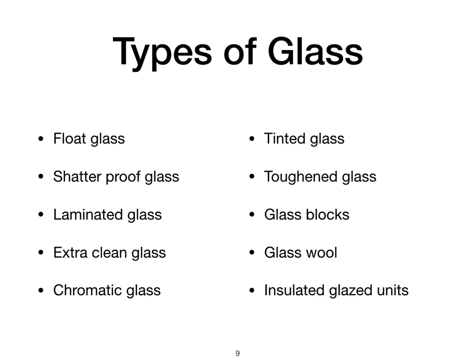Tinted glass. It is nothing but colored glass. A color producing ingredient is mixed to the normal glass mix to produce a colored glass, which does not affect the other properties of glass. For example, coloring ions like iron oxide, sulfur, manganese dioxide, cobalt, chromium, titanium, uranium are used as coloring agents, which give out different colors like green, blue, black, yellow, etc., and variations of these colors.